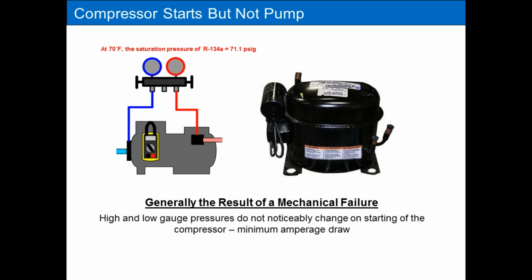And what I normally do is I unplug the unit first, stop the compressor, and I'm going to go ahead and put my gauges on. Now I'm going to normally have to put on a saddle valve. A lot of these systems are sealed systems that don't have access valves on them, unless they've been worked on before. So you're going to have to maybe put on a saddle valve to measure your pressures.